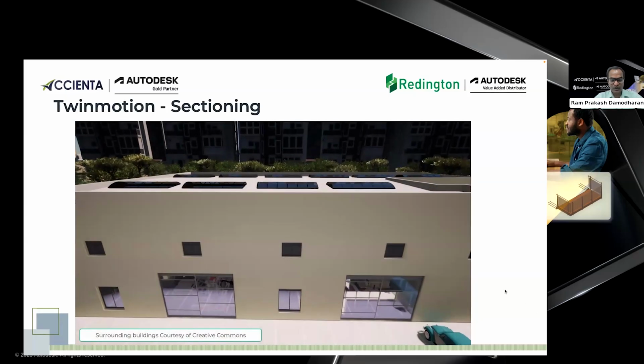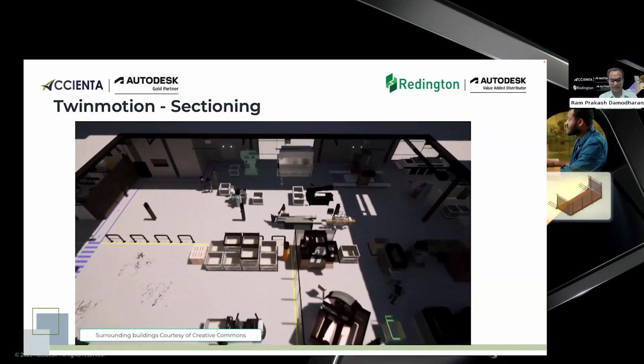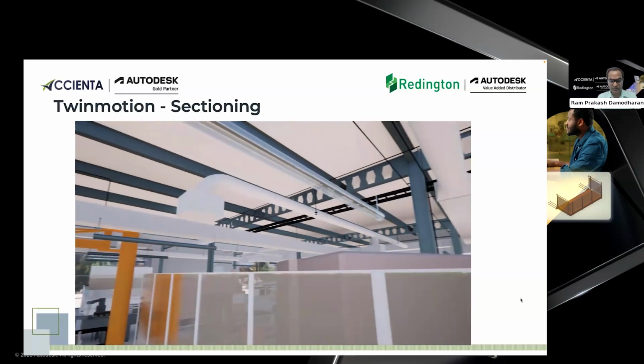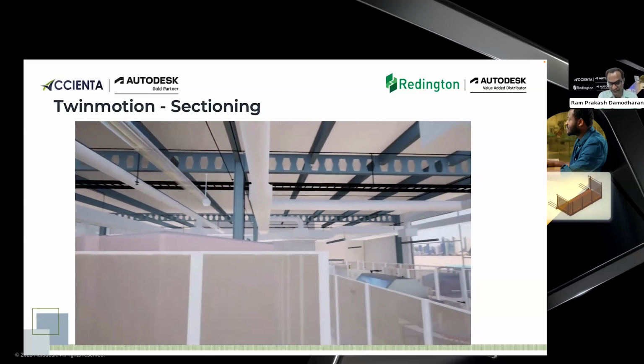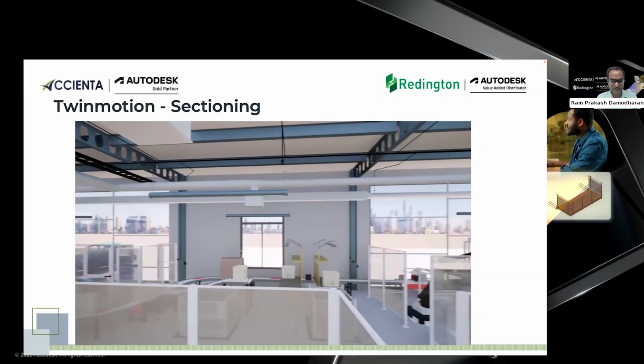This is again talking about more of the sectioning perspective. For example, you know that the model is developed in Revit, and Revit itself has section capabilities. But when it comes into Twinmotion, you also have the feature to make the section out of your model and view how the MEP services are placed, and what clashes may come up in future if you add more services, like adding an additional cable tray. Is there a space, or do you want to communicate with your structural engineer to talk more about having the space under the beam? Those section details are also available over here.